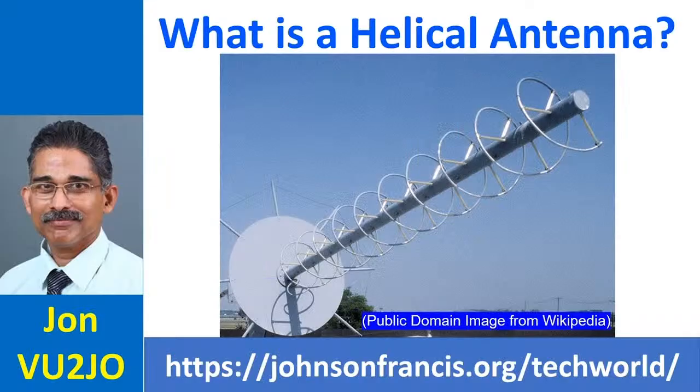Helical antenna, as the name implies, is an antenna in which one or more conducting wires are wound in the form of a helix. It is typically used in VHF and UHF ranges, with the most common example in amateur radio as the rubber ducky of handheld radios. Helix can be found inside the rubber ducky when the outer covering is removed.